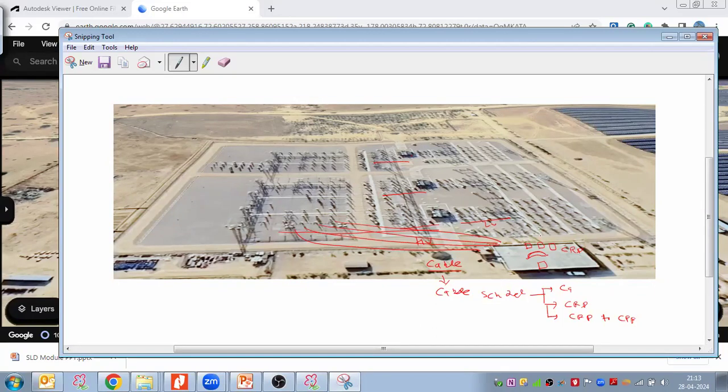So we do the cabling, and all the equipment status we take through the cables inside the control relay panels, and we have a specific device. This device is called the bay control unit, BCU. Sometimes we call it the BCU relay as well. The work of this bay control unit is to control each and every bay. Each bay has its own dedicated bay control unit.